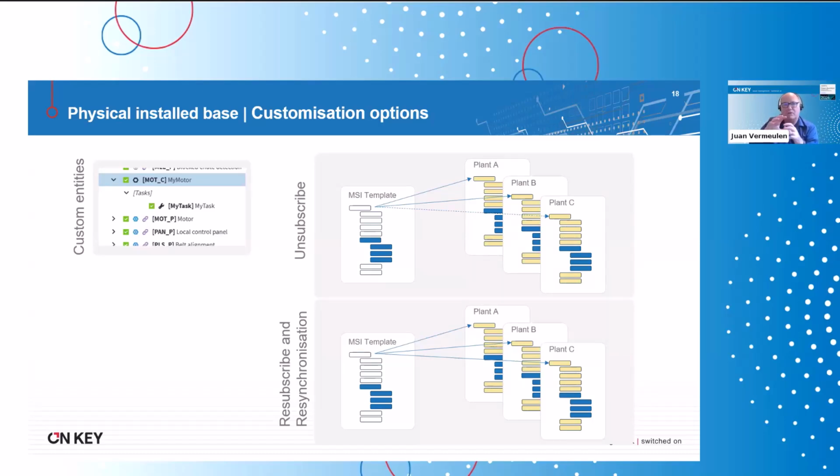So the customization is, as you see, that motor, that library item came through with all its parts and maintenance tasks, and it lies now there on your asset side. But nothing stops you from customizing that and putting your own items there. You can put in components, maintenance tasks, anything you want to do, and you'll see the difference is that the ones at the bottom have the little purple inheritance symbol on them, where your custom ones are just visualized without that.